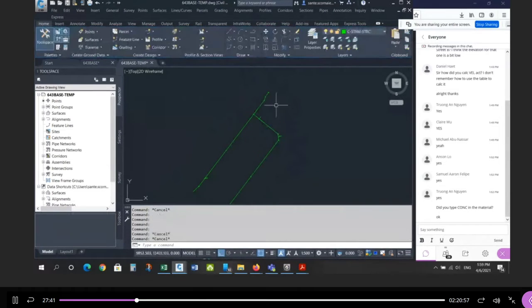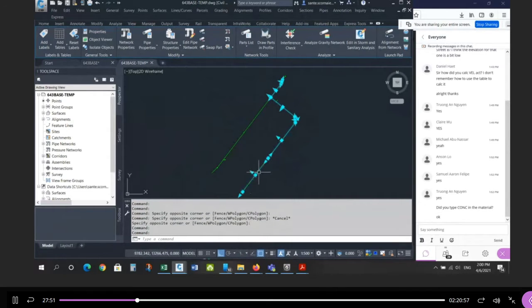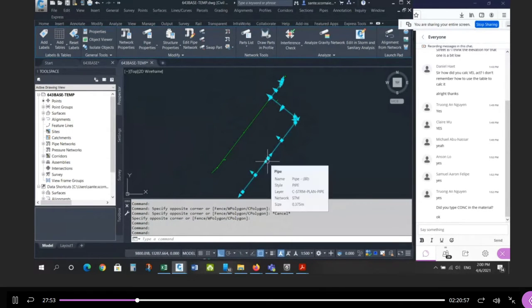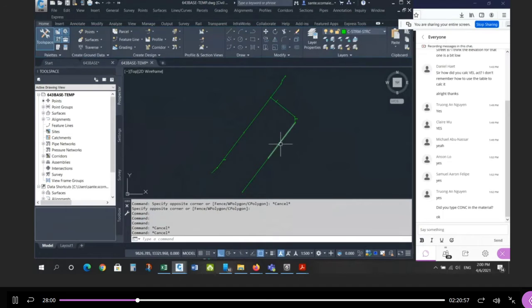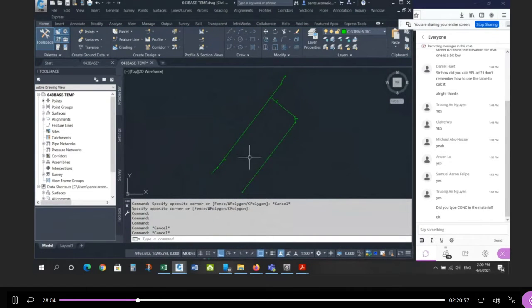Once you do that, recalculate all the inverts for all the pipes. 1, 2, 3, 4, and recalculate these with minimum drop as well, but keep them at 0.5%. So they'll get pushed down because the first 4 pipes are lower now. Okay, so these just are a vertical shift straight down. They're still 0.5%. So that's the revision.